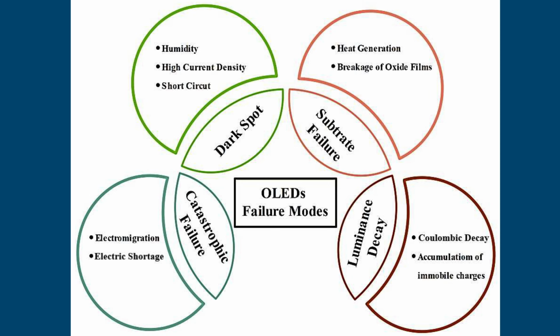Blue emitters are particularly susceptible due to high-energy excitons that accelerate bond cleavage and photochemical reactions. Thermal effects also play a critical role. Elevated temperatures can induce morphological changes, e.g., glass transition, and accelerate degradation kinetics.